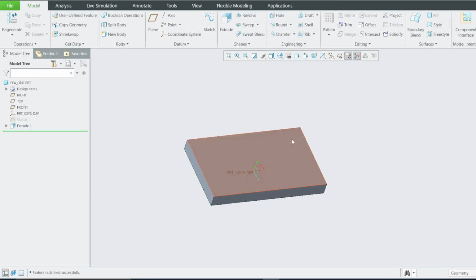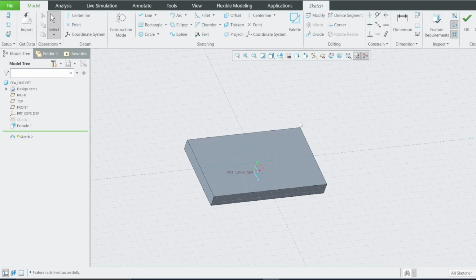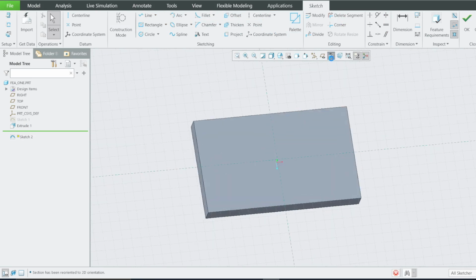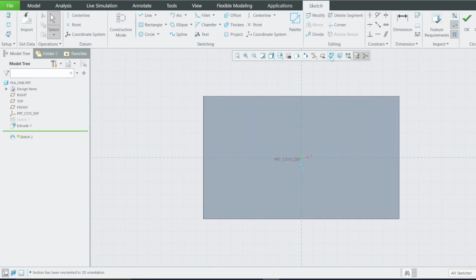I want to drill some mounting holes here on top. What we can do on that is I can use either the hole command, or I can extrude. Let me just extrude cut. In some videos I show you how to use a hole command. Then you can go to the orient sketch, this here, orient the sketching plane parallel to the screen, again center rectangle, like that.